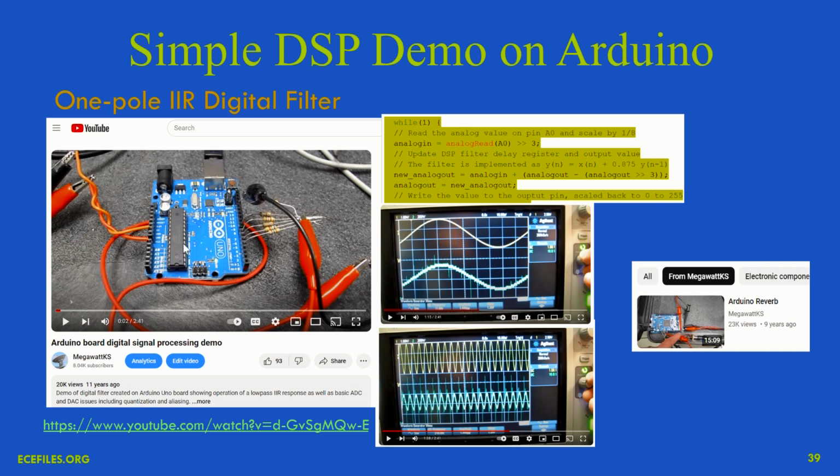And what was implemented in the code, which you can see in the upper right, a snippet of it, is a simple low-pass filter. I think it was about 100 hertz because I couldn't get the sample rate above 8 kilohertz for this thing. So these are very low-frequency waveforms. This is the input waveform to the ADC. This is the output of that filter.